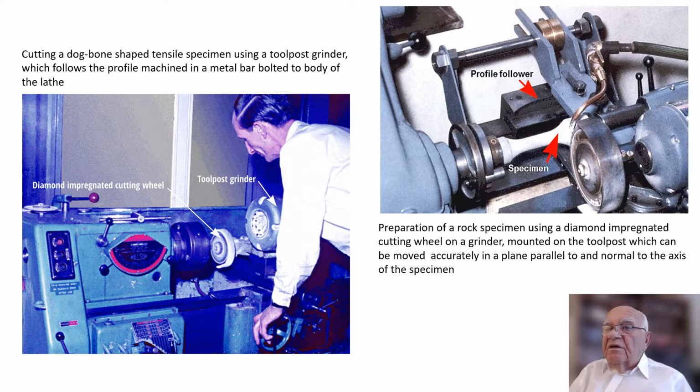In my experience, and based on my original training as a mechanical engineer, I prefer to use a lathe for all specimen preparation work in triaxial testing. This includes cutting and grinding of the ends of the specimen, as shown on the left, and cutting profiles of the specimen, as shown on the right.